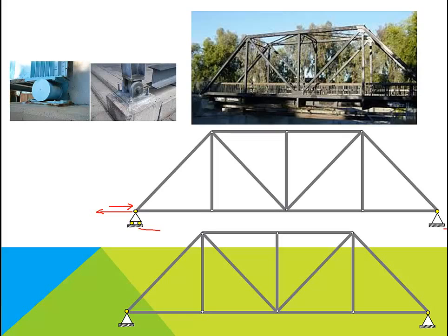However, if you do not put the roller support at one end but put the pin supports at both ends, then there will be no room for longitudinal expansion or contraction, which means the member has to resist such process. This may lead to deformation of the member. To avoid the member deformation, larger members and stronger supports are required. This will increase the cost of the structure.